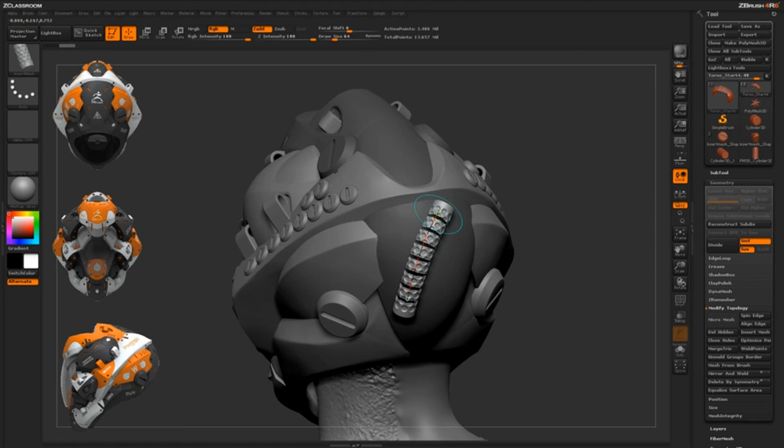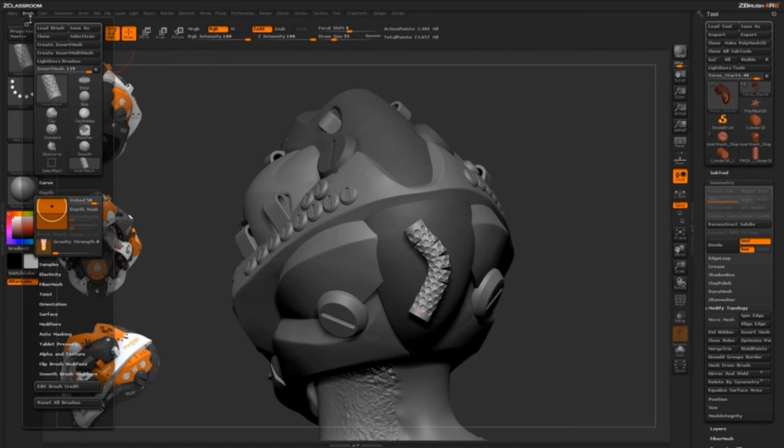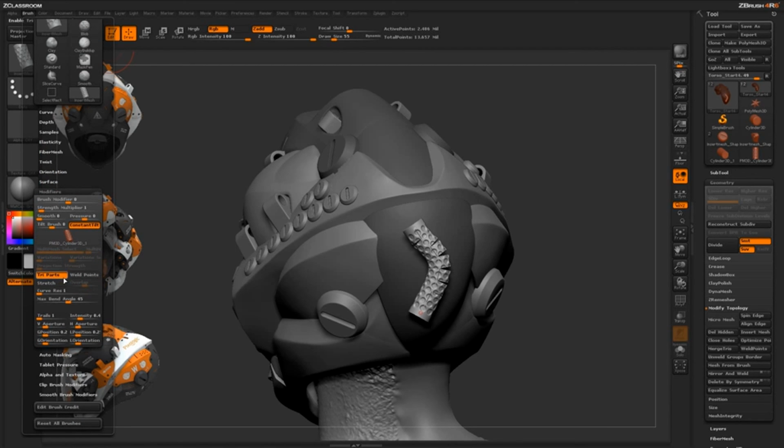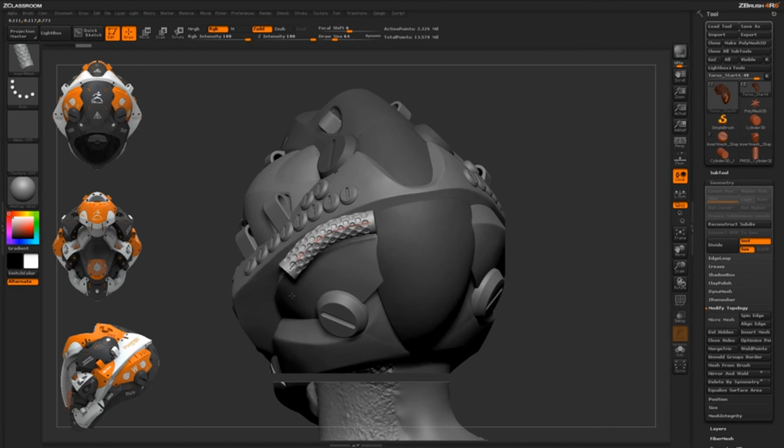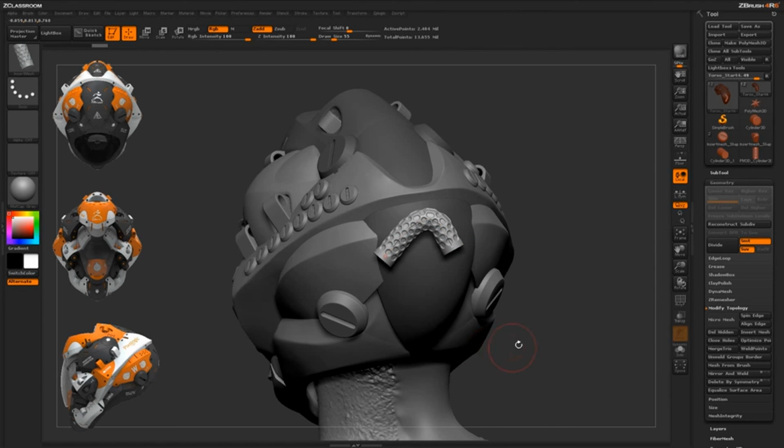Now with this kind of shape drawn out, I can come through and start conforming this, but it's not really giving me that precise cylinder shape I want. So you can see I have these kind of unwelded areas in between. Well, if you come over to your brush menu now and then come down here to the actual modifier menu, down here there's weld points. So if I click weld points and then come back to my actual curve and update, it's going to go through and weld those points. So now you can see I've got that shape all welded together, and you can kind of move it around the surface of your model.